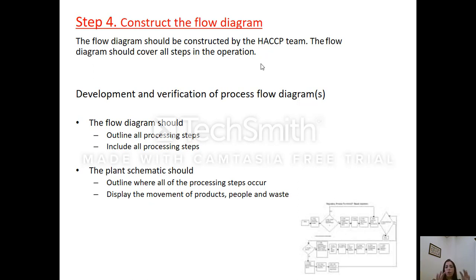The second step will be, for example, the mixing of the different ingredients, and we need to specify the mixing temperature and the mixing time. Following the mixing, maybe we can preheat the product by heat exchange. So we can put preheating in a heat exchanger. Then we will pass to the filling step. If it's a hot filling, you also need to mention the filling temperature.